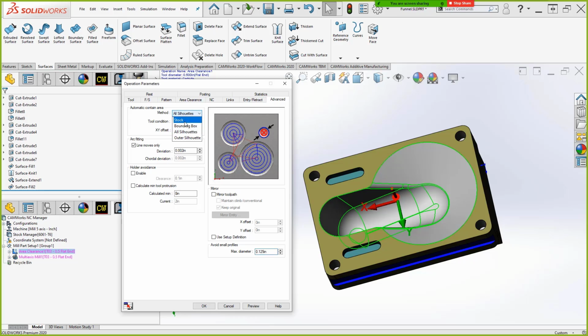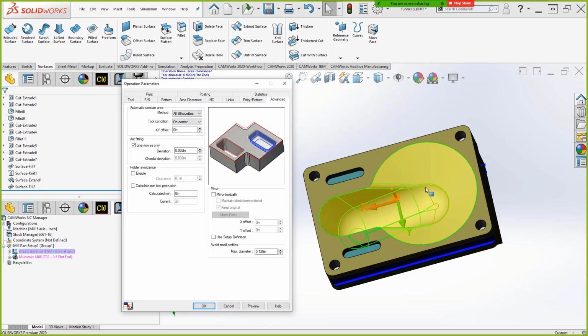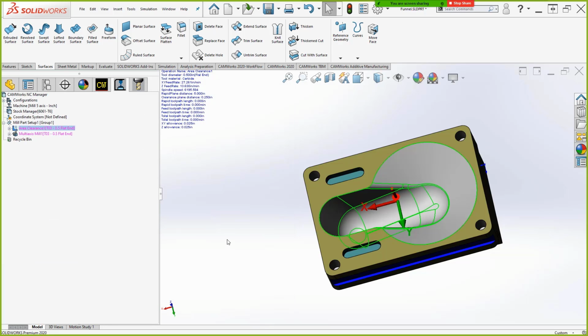But now with this preview, you can better anticipate what to expect before you hit this preview button and maybe wait around. In this case, maybe 10 or 15 seconds. In some cases, it gets far more complicated. You might be waiting 30 seconds or a minute for a toolpath to generate, only to realize this stuff was set incorrectly. So it's good to test that stuff, know about it before you hit that generate toolpath button and possibly be sitting around for a little bit. And sitting around for not good results, for inadequate results.